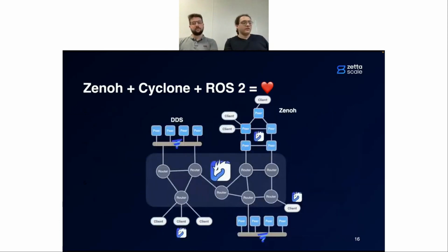And so, here, for example, is just a sample topology, right? Mm-hmm. Where you're using Zenoh and you have these DDS islands that are present here, right? So within those islands, you have, for example, the quadratic discovery happening still and other things like that. But then Zenoh, its discovery, for example, is much more laser focused, and it's able to bridge those two DDS networks. And you can use traffic shaping to ensure that only the stuff you care about sharing between them is shared between them.